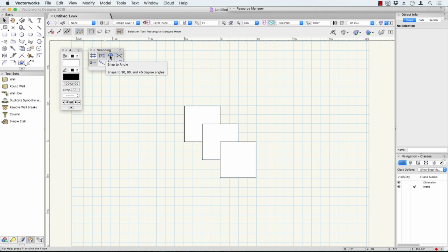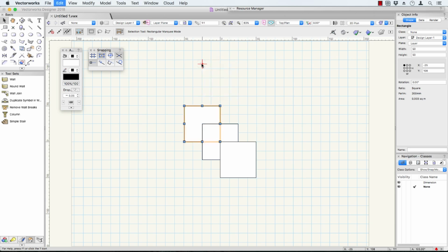When you move objects, I don't know if you noticed, but when I moved that object, I ended up with a guideline. This guideline here, that's a smart cursor guideline. A line V, that's another smart cursor guideline. So I get several guides that come up. This angle snap is a great guide. It allows you to make sure that your lines are going in the right direction or they're constrained to certain angles. This will find intersections.